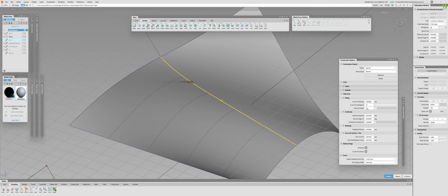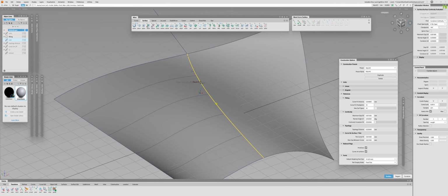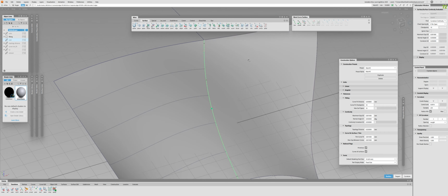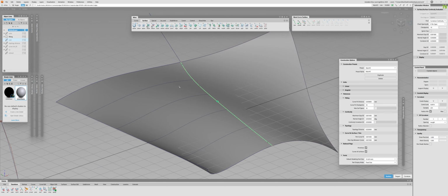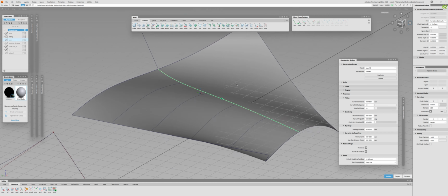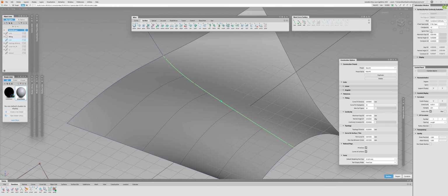And this one is the standard one, which it basically uses by default. Now you don't really need to be crazy and go to 100 all the time, because in most cases this is excessive, and in most cases 10 is more than enough. If you have this 10, its curvature, you see that surface continuity tells you that everything is all right, and you use your diagnostic shadings, and if you see some discrepancies, then you increase the amount of checkpoints. But this is a rare occasion. In most cases it's supposed to be okay. But if it's not, well, you know where you can check this.